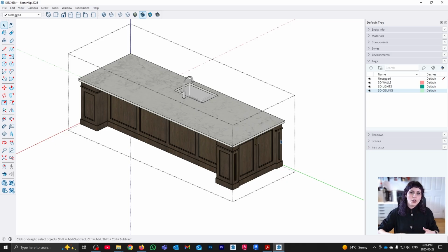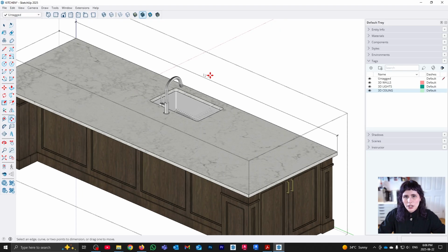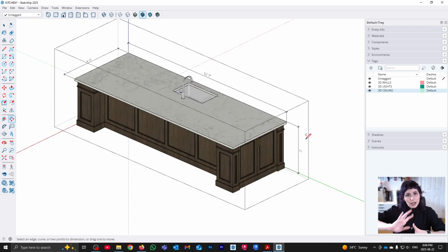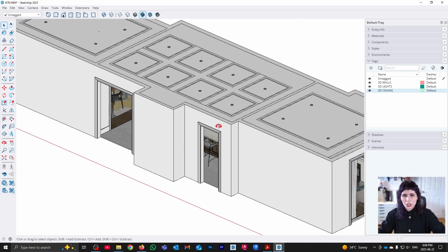An isometric view maintains consistent dimensions, which means that if I wanted to, I could come here and put a dimension here. That's not looking super hot, we're going to talk about those later. But I could put another dimension here, and then another dimension here, and pull this one out. So the idea of an isometric view is that, technically speaking, you can annotate it because there is no perspective distorting distances, spaces and dimensions. That is the main reason that we work with parallel projection, aka isometric.